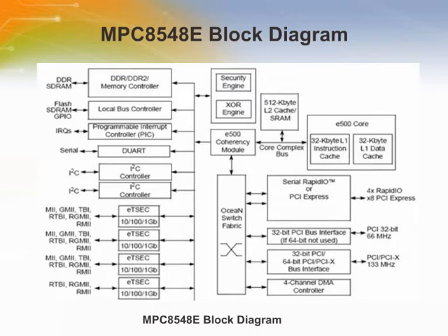Support for these high-speed interfaces enables scalable connectivity to network processors and/or ASICs in the data plane where the PowerQUICC handles complex, computationally demanding control plane processing tasks. These processors also feature next-generation double data rate or DDR2 memory controller, enhanced gigabit Ethernet support, double precision floating point, and integrated security engines that support the Kasumi algorithm needed for 3G wireless security.